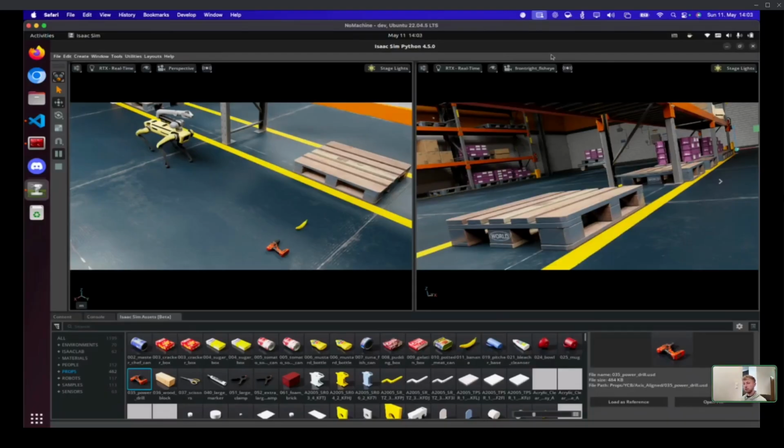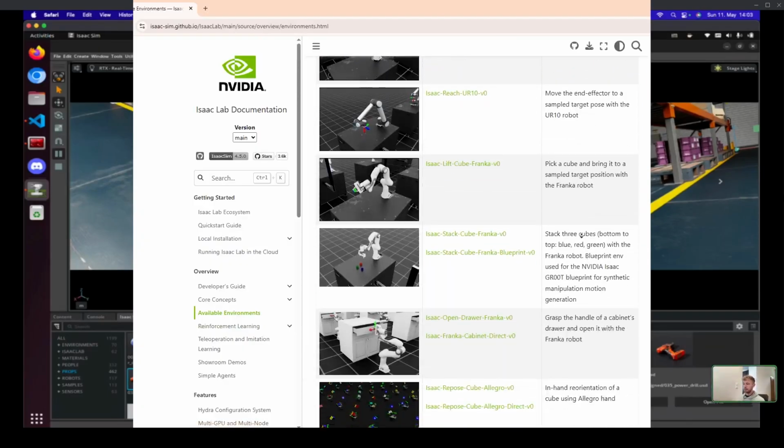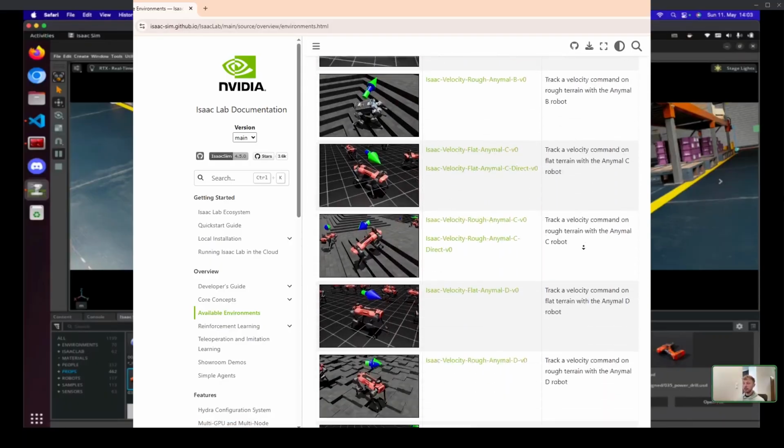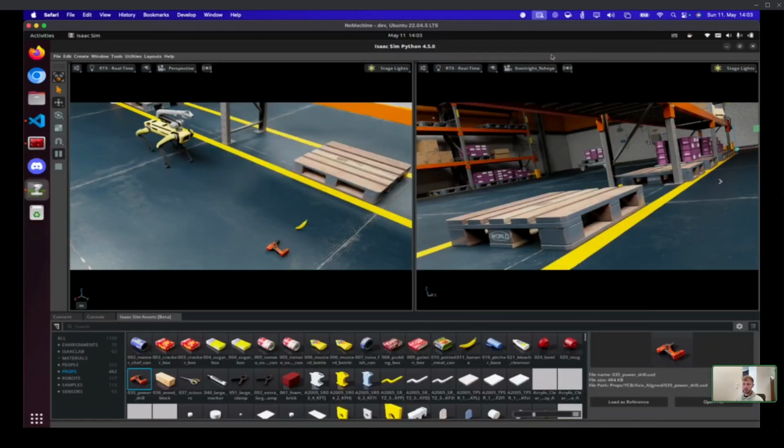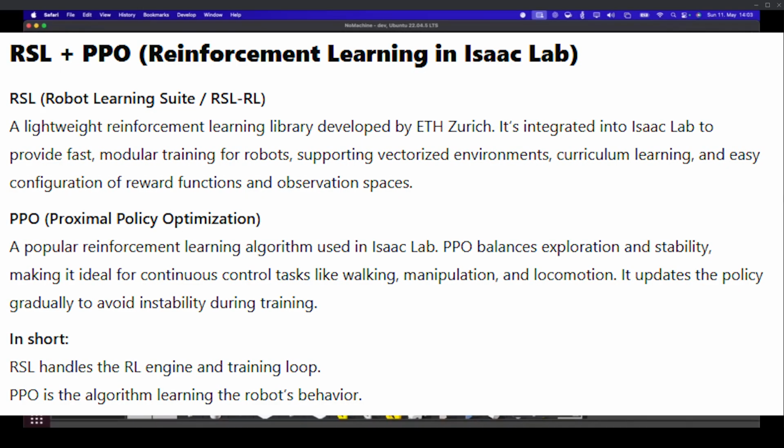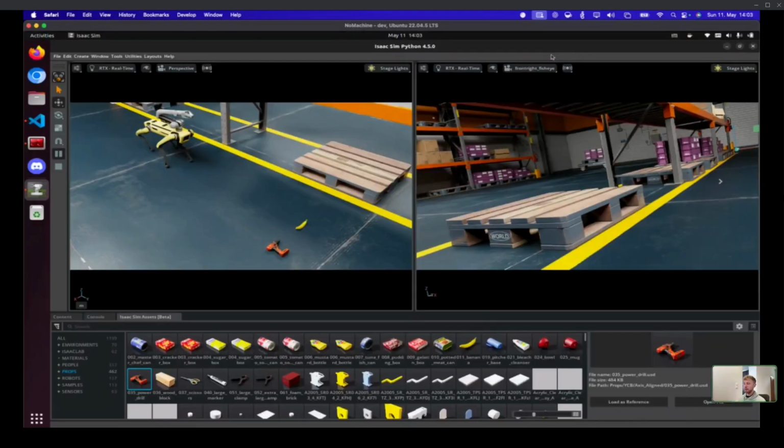Yeah, sure. So yes, as you said, I trained it in Isaac Lab, which is built on top of it. And in this case, I took the public example from Nvidia and Boston Dynamics as a baseline, where they utilized the RSL-RL PPO algorithm, which is an optimized PPO algorithm, doing pretty well and fast computations on GPU.